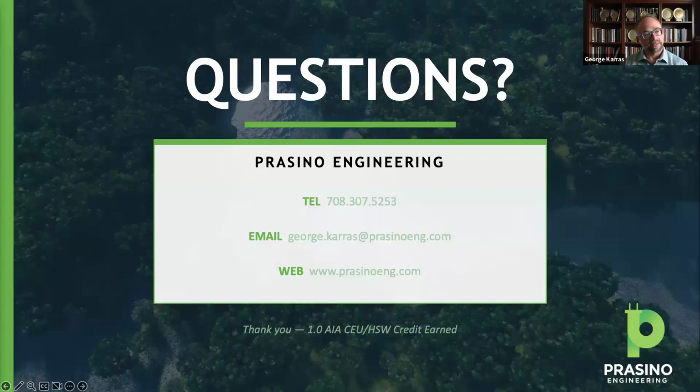Yeah, and John, to add to that, since that was a clarification, I think Jason actually just mentioned it there. It doesn't require unit compartmentalized testing. If you were to contract with a typical pressure building tester, you would still just do the envelope because that's what's required, and then go from there. It's no different than a school with lots of classrooms. You're looking to pressurize the total building area. So if you can get within those square footage thresholds that I mentioned earlier, you're fine, right? And if you can't because of the size of the building, I'd tell you to do third-party review.